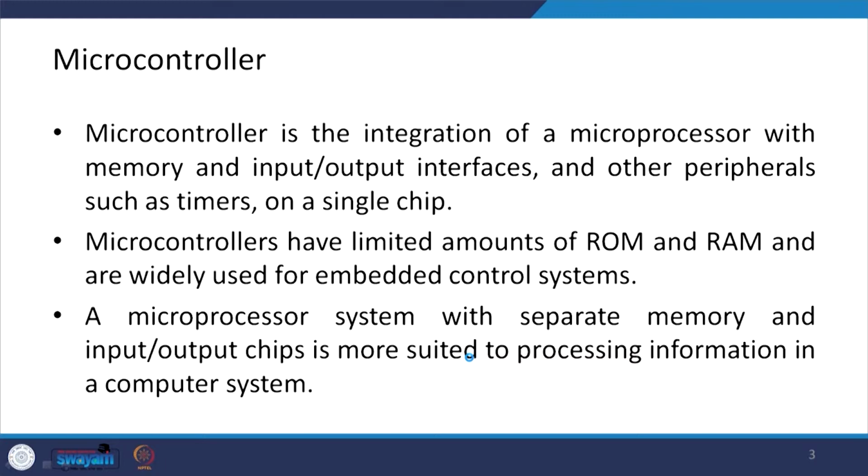Microcontrollers, as I explained to you in my previous lecture, is an integration of microprocessor with memory and input output interfaces, and other peripherals such as timers on a single chip. The microcontrollers have limited amount of ROM and RAM and are widely used for embedded control systems. A microprocessor system with separate memory and input output chip is more suited to processing information in a computer system.